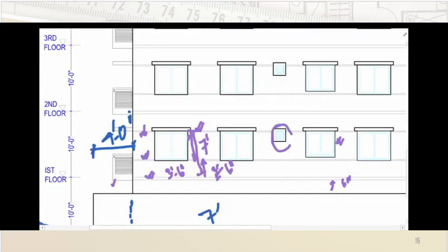So this is something smaller than the other windows, and obviously the toilet one will be smaller as well. So in each case you will take these sunshades. So sunshade dimensions, you will extend it up to not more than 1 inch, better to take 0.5 inch if possible, and the thickness of this sunshade you can take 4 inch, as we have said earlier, for all these sunshades.